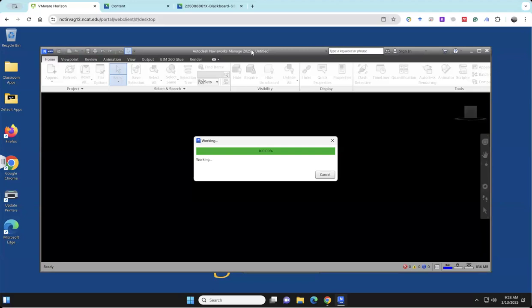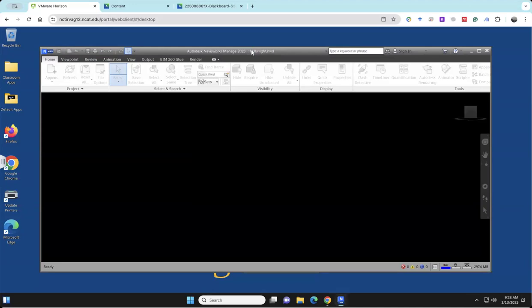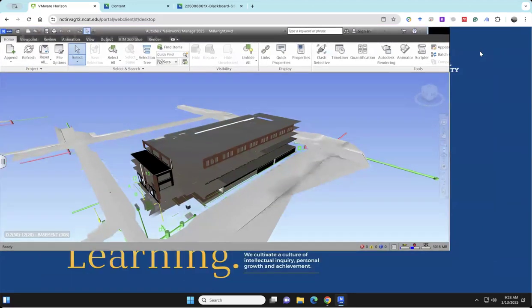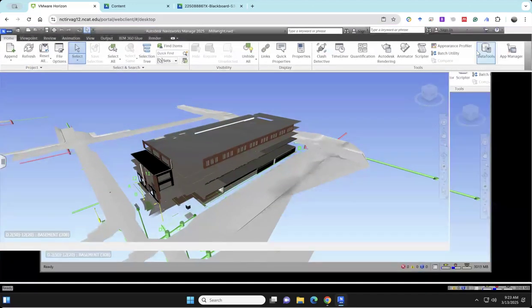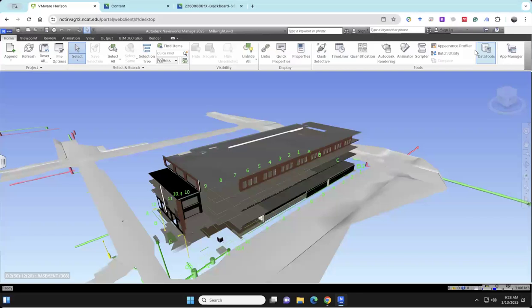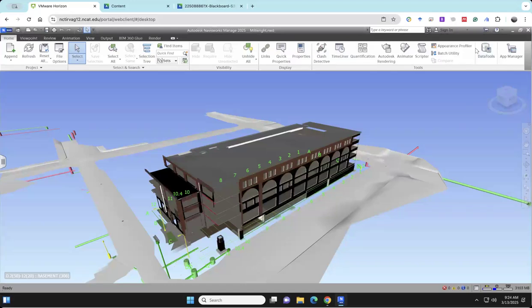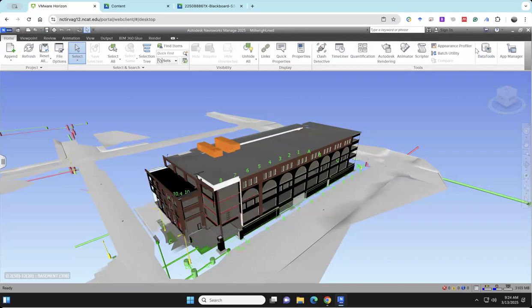It says 4. WF1 is the strip footing, it's wall foundation, WF. The one means you may have multiple of different sizes, and one is the first one in your model. And the brace 4 means you need 4 pieces of it.